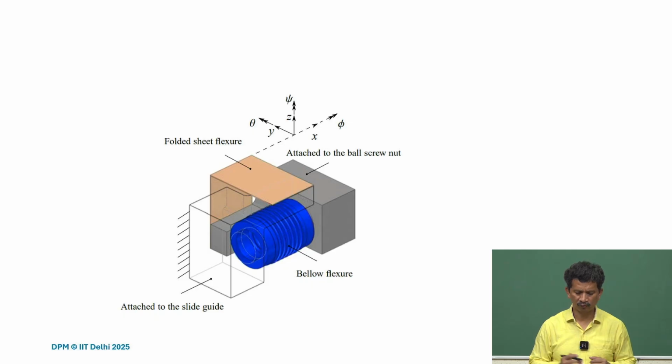So we have the axis for the ball screw, but at the same time the rotation unit or module is moving on a linear guide. So we have another axis. We have two axes and we have to assemble them, so definitely we have to take care of the misalignment and the offset. We wanted to address that, and then based on the requirement, what we found is that the requirement is just to push from the ball screw.